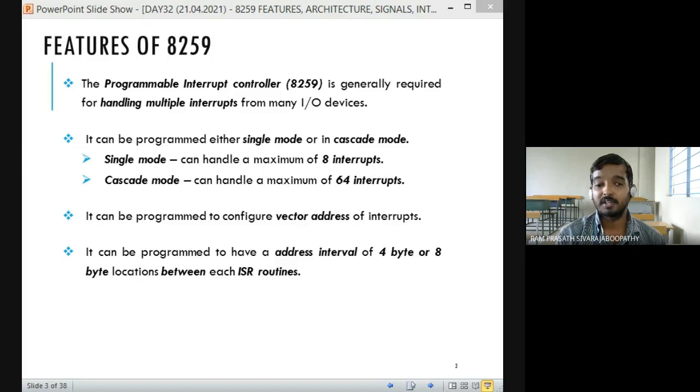You are representing it as a binary pattern. Kindly correct it. Addresses we generally express in hexadecimal. It is a 16-bit address, so it is difficult to represent 16 bits in binary pattern. So we always represent it with a 4-digit hexadecimal value.